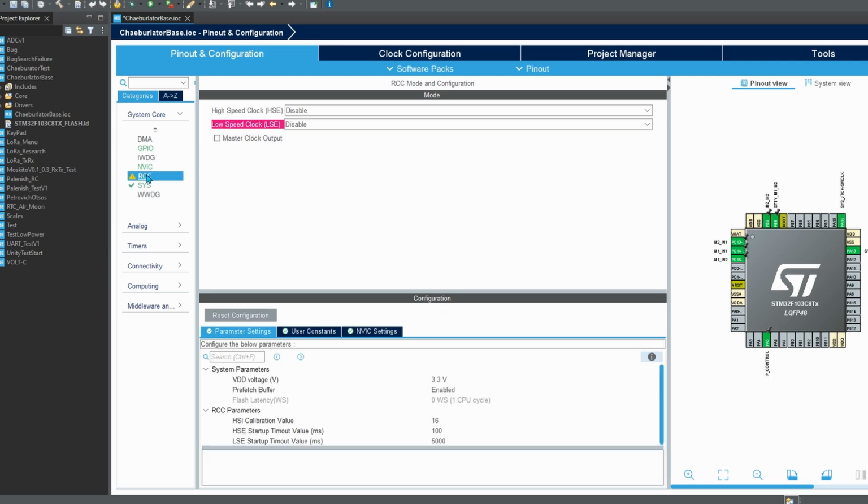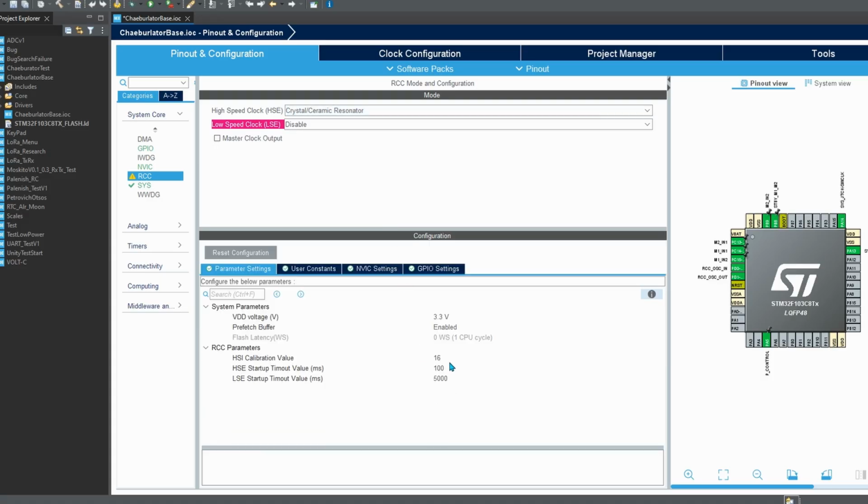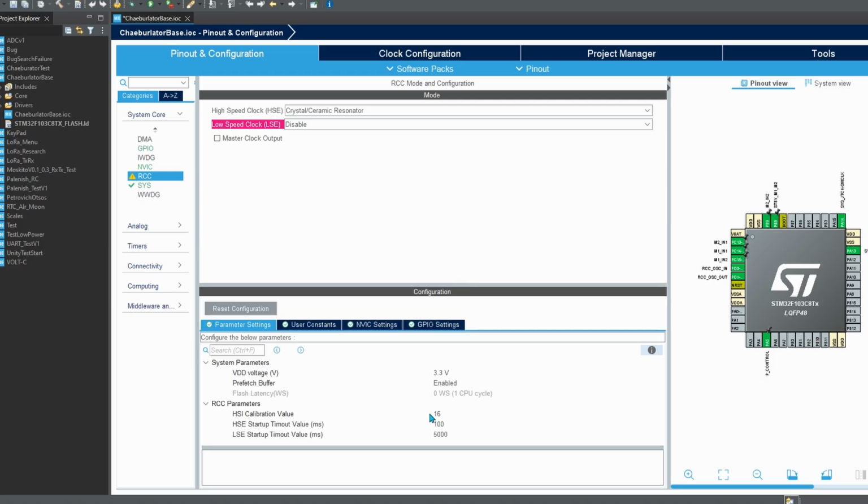We will set the system clock using a quartz crystal oscillator. We won't change anything here. I've already tested this crystal with these settings and it works great. However, at the low UART speed I typically use, I think you can get by without the crystal. Everything will work just fine.